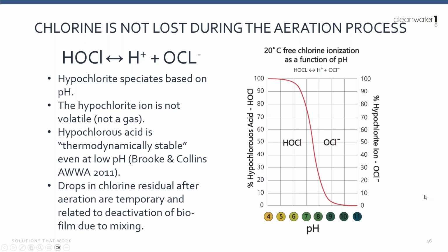All right, I think I got time for one more. Oh, it's 11. I'm going to sneak one more in here and then I'll let you guys go. Is there any smell with the ventilation of the trihalomethanes? We're looking at installing near homes. No, there is no odor associated with this. However, there can be sound. So when you're running a ventilation system on top of a tank, there can be a sound footprint that you should be aware of. We've got some math that we can use to tell you how many decibels you're going to be hearing at the property bound. And we also have sound attenuating closures that we can put around the active headspace ventilation systems, but that is something to pay attention to as you put these together.